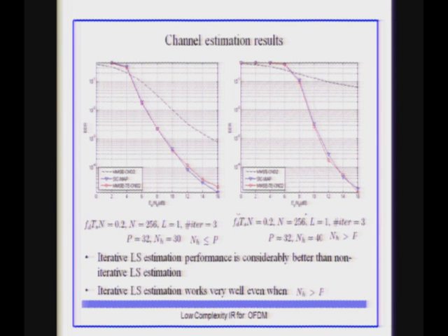These results are for error probability. I know in a practical system, if I'm a user, I only care about performance and error probability. If you're doing channel estimation, you have a simulation test bed already. Have you looked at taking a stored record of your channel behavior under these simulated conditions, take a look at your channel estimation result, and compare the channel estimates versus the actual channel behavior in the simulation run? I haven't. The proof of the pudding of the channel estimate would be really more proven there than in the BER wrapped up in some larger fashion. I mean, they kind of correlate, but it's not quite the estimation problem.